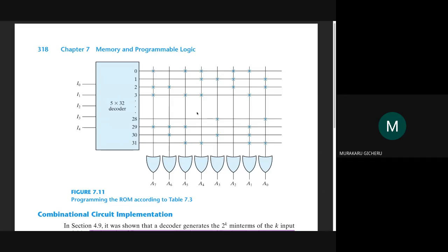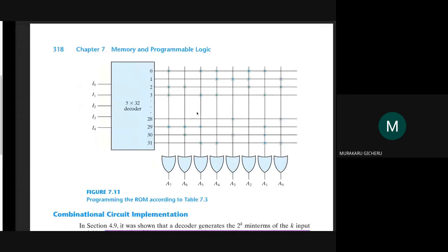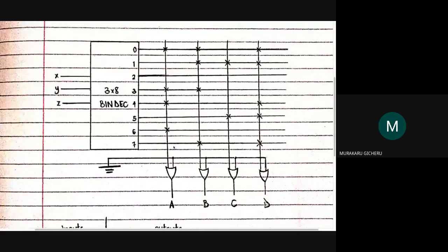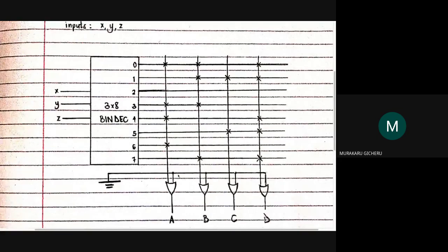You can compare it to this diagram of mine, where I've put dots here, here, and here. There are 3 dots over here, showing that this connection between this OR gate and this ground, and this OR gate and this ground, and this one will always be there, no matter what, unless I literally break this whole thing into tiny pieces. This connection will never change. But these ones with the X's can change because of fuses. It's just that since we want our ROM to store certain information, we leave them intact.